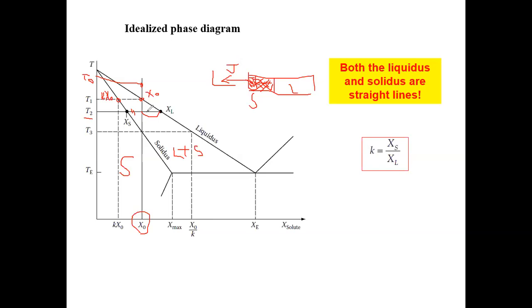So what does this mean? This means that for alloy solidification, it's not sufficient to just cool the system to a single temperature. If you want to impose an equilibrium growth of the solid phase, you have to slowly but continuously cool the system from T1 all the way to T3. Does that make sense to everyone? Only through this process can you cause the equilibrium growth of the solid phase that propagates from the left end where you take the heat away all the way to the right end, where the entire system transforms into the solid.